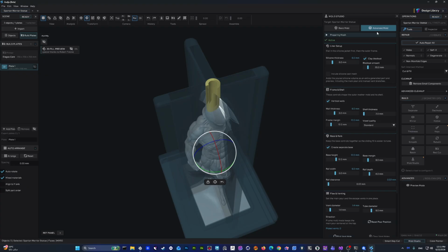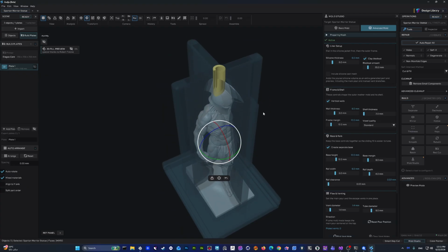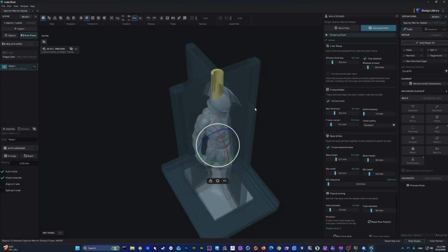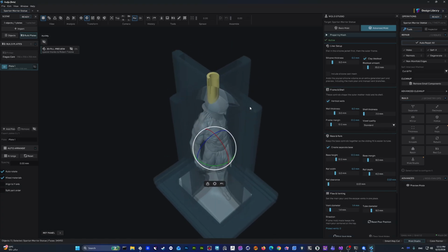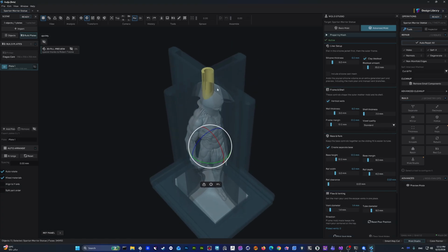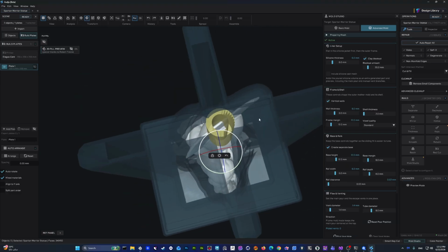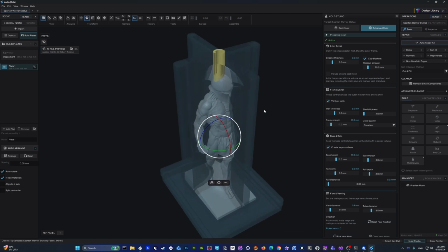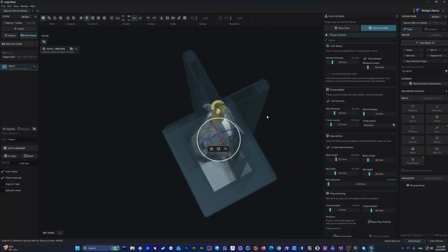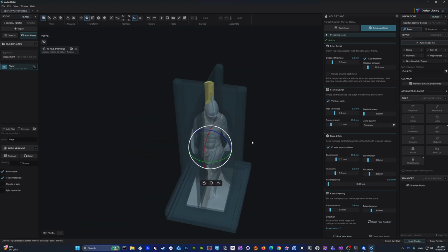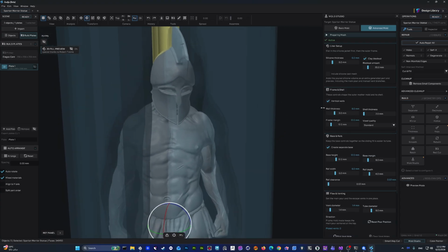But for the advanced mold, at this stage, we're actually creating the mold of a silicone one, not the final pouring material you will put inside the statue. So we are creating the silicone mold, or this method called mother mold. We are creating the mold of the silicone we're gonna use in real life. So you have full control on the wall thickness.